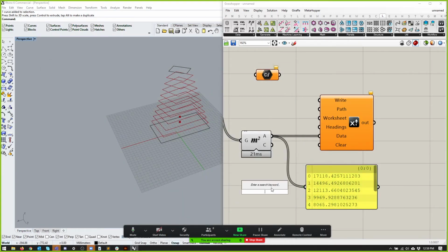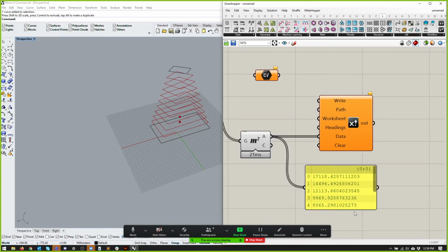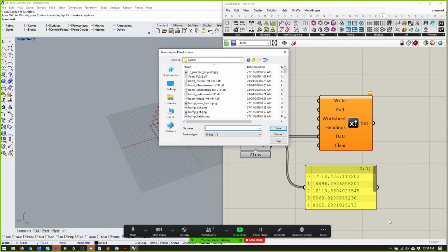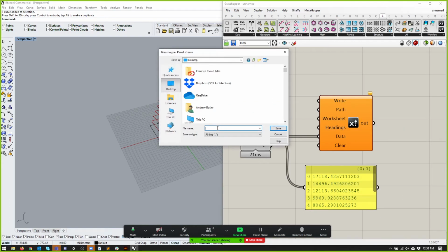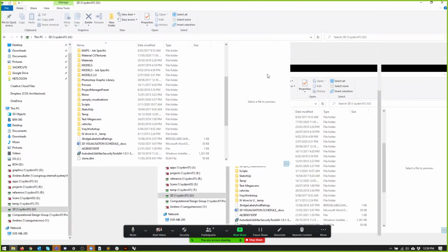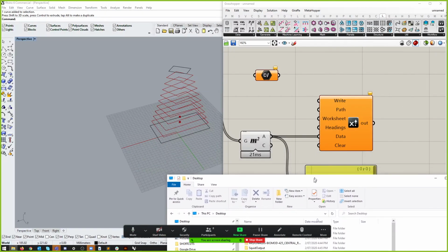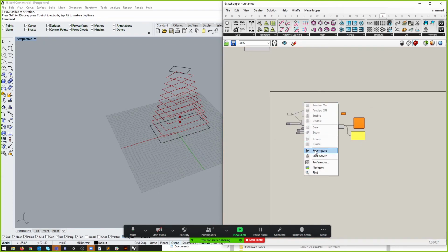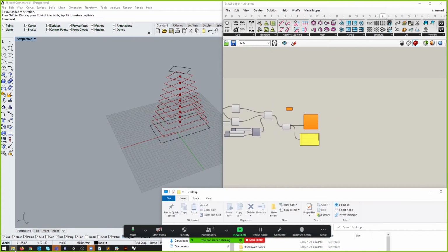So if you right-click that panel, there should be a stream contents. Yeah, you can stream, which is the same. You can literally tell Grasshopper to write a text file. You can even change the export to CSV, and you can type whatever. And now if you run, you have to run the script again. Unfortunately, I don't think it does it immediately. Recompute, or F5. Yep. Cool. Now there's a file where you told it to save.